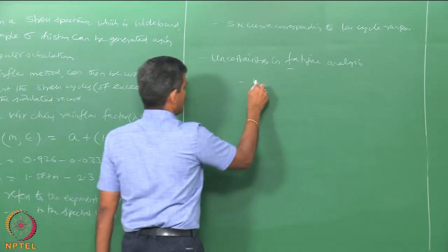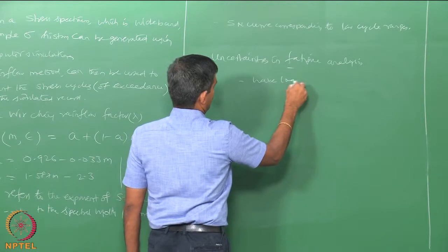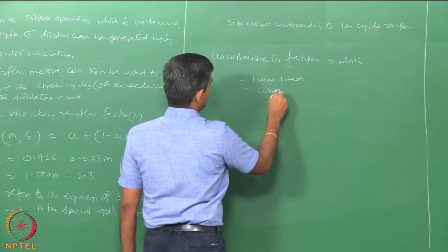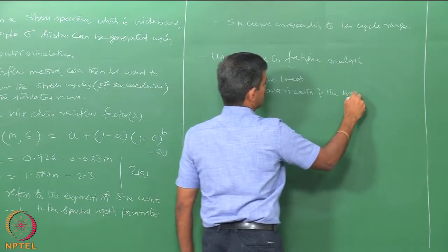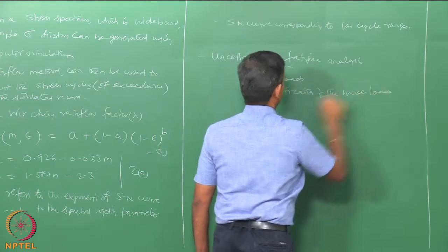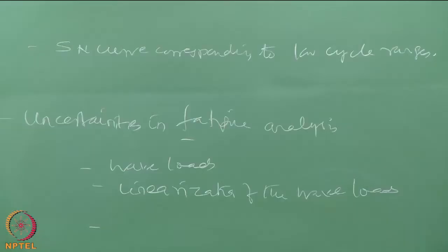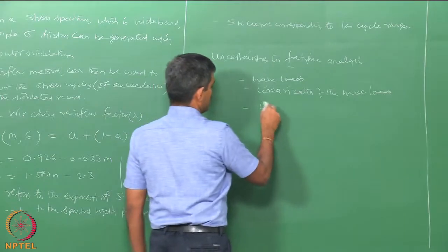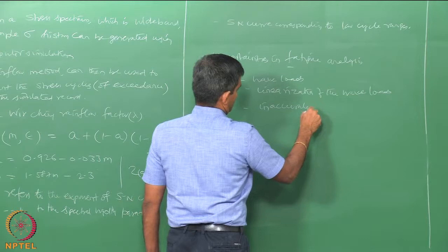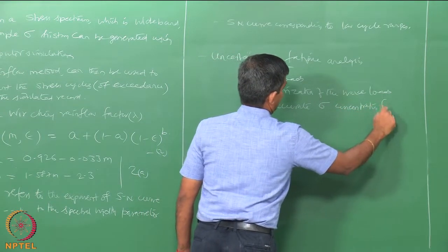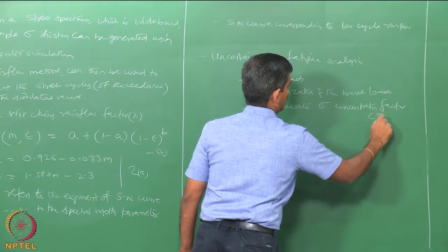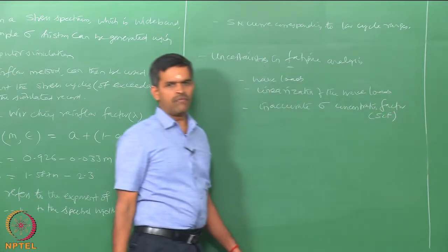They may arise from the wave loads, essentially the linearization of the wave loads, which can be one major problem. Inaccurate stress concentration factors, what we call SCF.